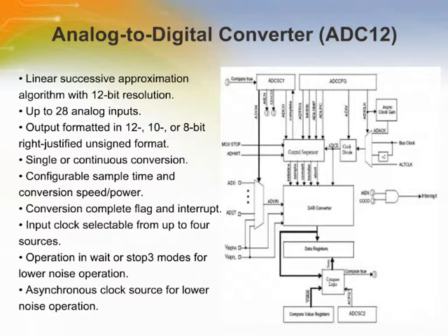The conversion complete flag, COCO, is then set and an interrupt is generated if the conversion complete interrupt has been enabled. The ADC module has the capability of automatically comparing the result of the conversion with the contents of its compare registers. The compare function is enabled by setting the ACFE bit and operates with any of the conversion modes and configurations.